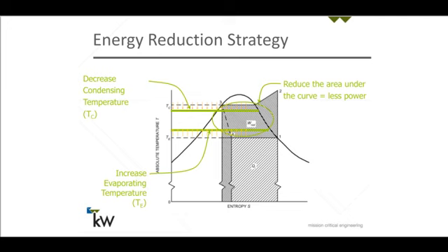For any piece of refrigeration equipment, you've got a temperature entropy curve that governs the performance. Q, the rectangle in the chart, is the cooling that's generated by the refrigeration equipment, and what's identified as W is the work done by the refrigeration machine. So for whatever Q you need, however much cooling you need, the refrigeration equipment has to do work. So how do you lower or reduce the amount of work that's done by that refrigeration machine?